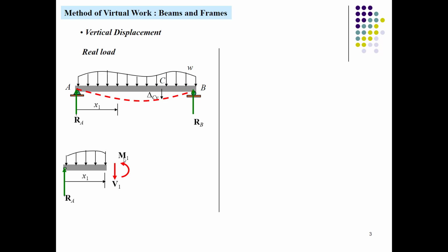For example, we have a shear value which comes up as V1 equals negative something. Then we will see that our assumed direction, which is downward, is wrong, and you must take it in upward direction. But conventionally it would be taken as downward on the right section of a beam, and the moment would be counterclockwise at the right section. Conversely, it would be upward on the left section of the beam and clockwise in the left section.